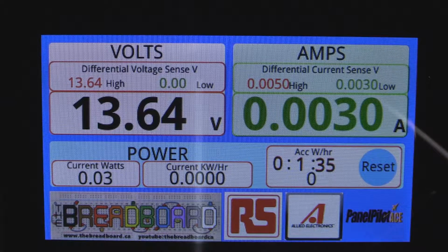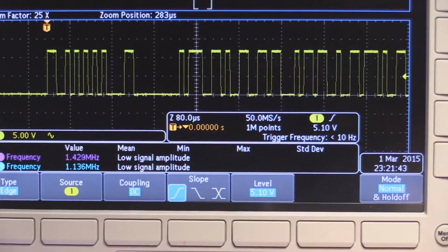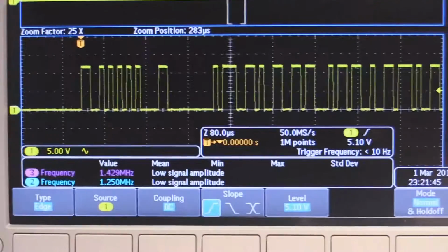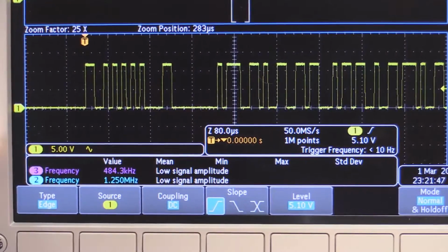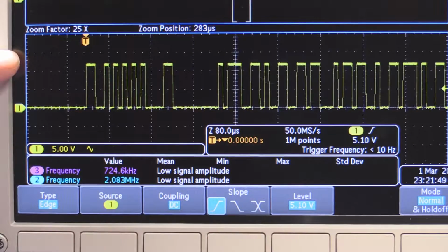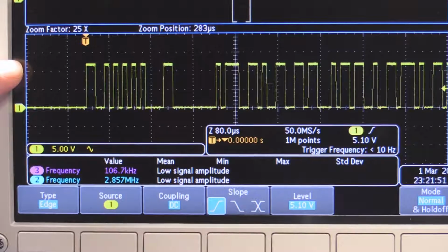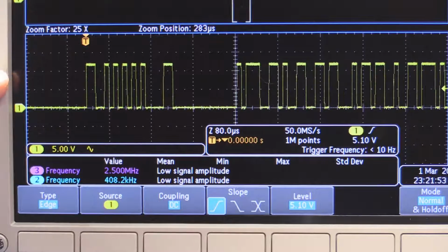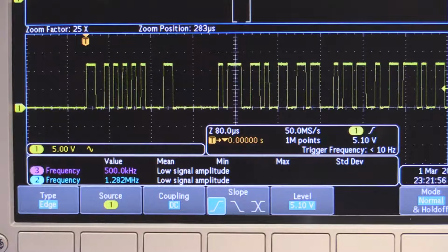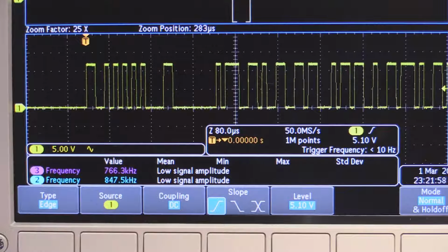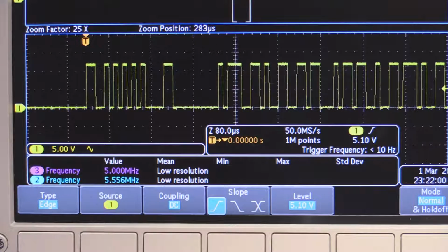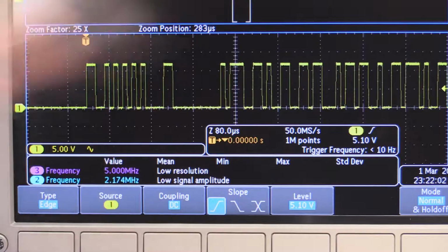Now, the other thing that I've got happening here, which you can't see down here, but which you can see if I take you up to my oscilloscope display, is a live feed of the RS232 output. It's set to 5 volts per division, so we've basically got about 12 volts coming out here. Now, as I said, I haven't got anything that's going to actually allow me to show you the RS232 coming out,